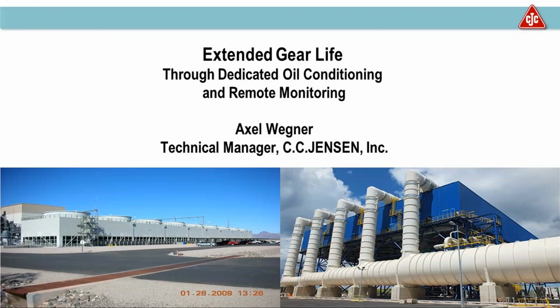So say if you have 40 fans or 40 gearboxes with a sequencing valve, you could just pull samples off of each gearbox instead of having a mobile cart. Have a stationary analyzer and somehow pipe that to each of the oil reservoirs to pull the sample out, and then have maybe 40 sampling valves actuate every 5 minutes or something, and that way we can have a continuous oil particle reading.